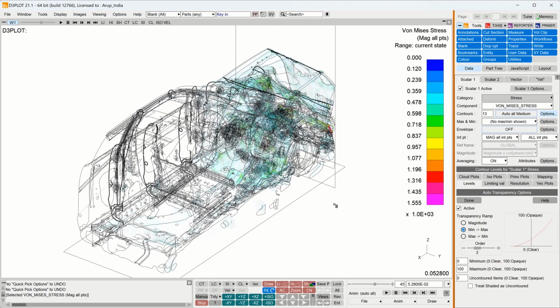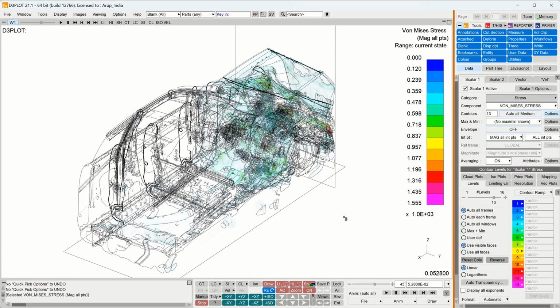Although entities can be blanked to reveal these hidden parts, this is sometimes unsatisfactory as a solution. By varying the transparency of entities, it is possible to view these minimum and maximum values while still having the entire model visible within the graphics window. Automatic transparency could be used in automotive front impact analysis as shown, where you might also want to plot forces in beam elements, and to use auto transparency to reveal load paths through the structure.